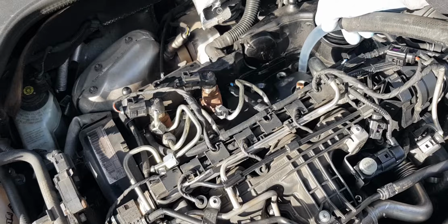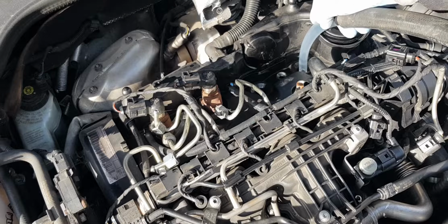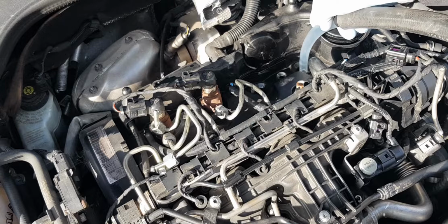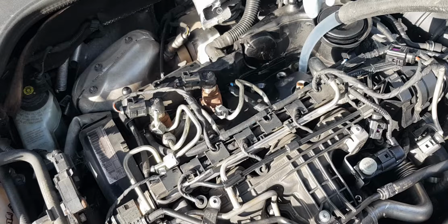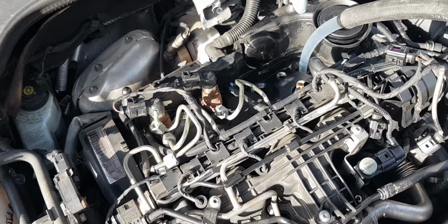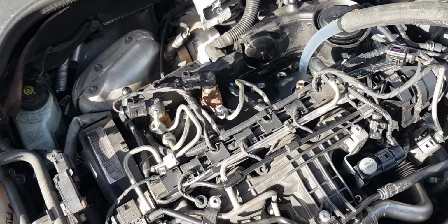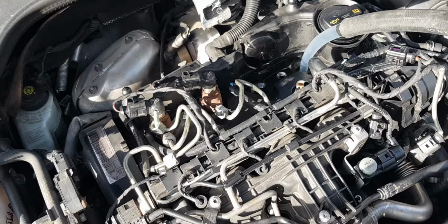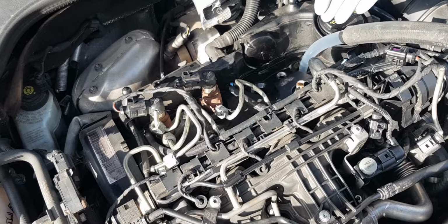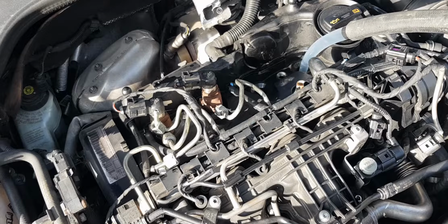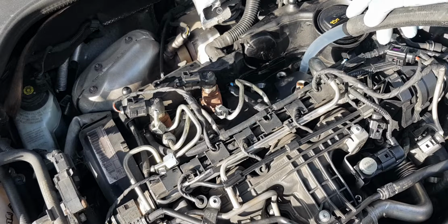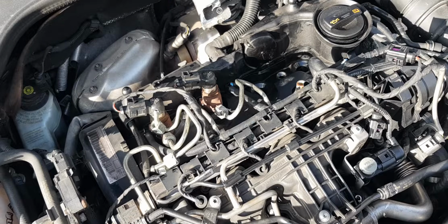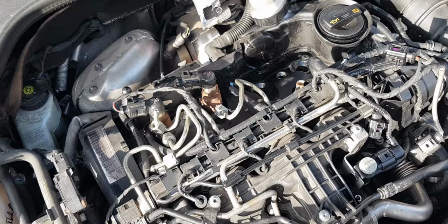I'm going to be spraying brake cleaner a tiny bit. Be careful because you have your camshaft there, so you don't want to put too much. I'm going to vacuum first, and then literally a couple of milliliters of brake cleaner, and then I'm going to suck it out, spray and clean at the same time. So I'm going to do one side first, and then I'm going to show you the other one, just so you can see what I'm doing.